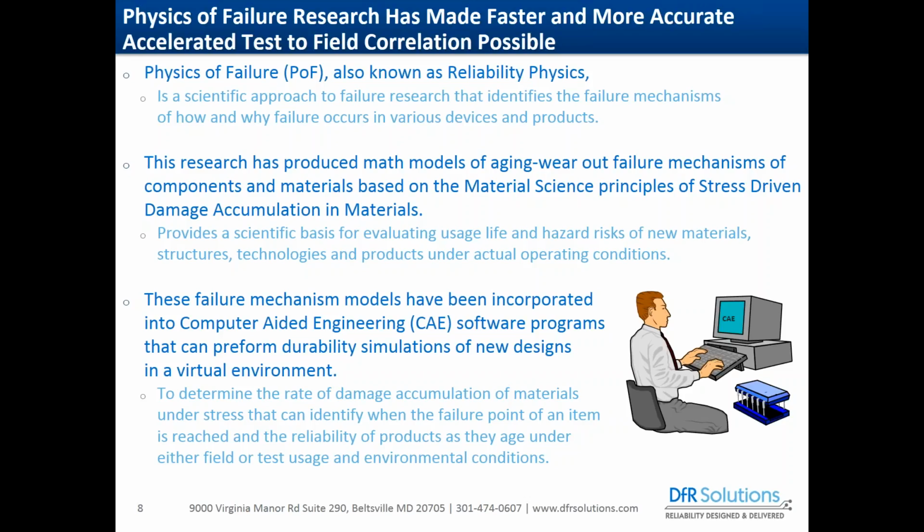And we'll be describing how we can do the simulation under both the expected field service life usage conditions and compare that to a design of experiments, if you will, of various test configurations in order to come up with a test that produces an equivalent amount of stress-driven damage aging that would be experienced over the intended design life in the field.